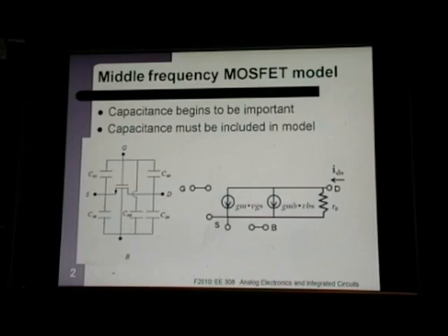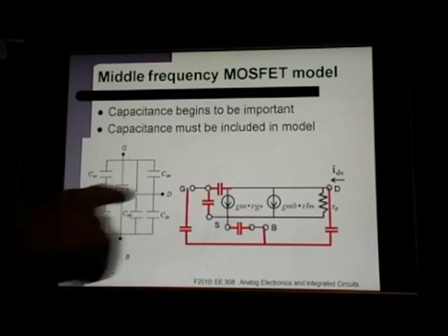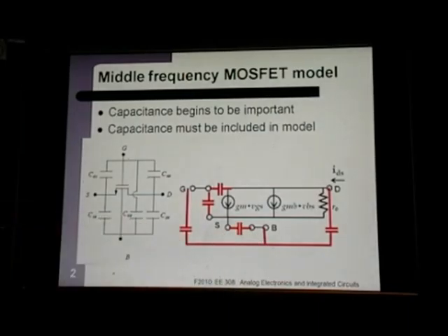When we looked at our MOSFET, we found a whole bunch of capacitances. These are the total possible capacitances, and we don't see all of these when we are in the active region. For example, the gate bulk capacitance does not exist because you get a layer of charge in the channel, and that charge is actually, if you look in books or on the slides, considered gate source capacitance. So the gate bulk, because the gate is coupling to the charge in the channel, it doesn't see the gate bulk, and this capacitance goes away.